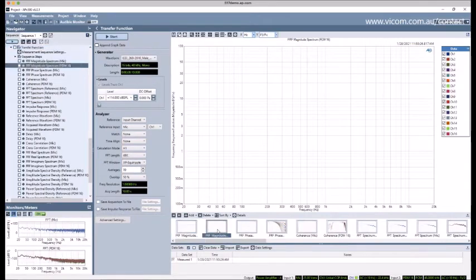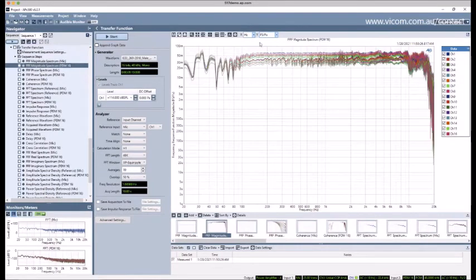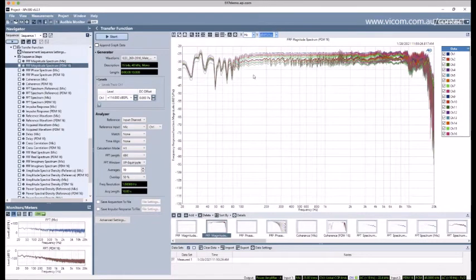We're not interested in that so much, but here we have the frequency response function between the 16 PDM inputs, all 16 PDM mics, and our reference microphone. And you'll notice, number one, this is going from 20 Hertz to 20 kilohertz. It's full range. And these responses at low and high frequency look a little bit janky.